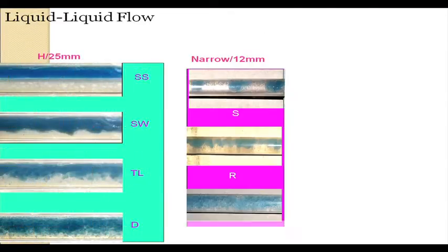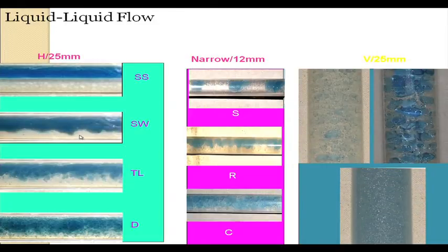Now, in this particular case, we find that due to the higher surface tension of the liquid, it cannot assume the shape of the elongated plugs as we observe in gas liquid cases. On the contrary, when the waviness is very much, then it shears the interface, and therefore, there is a large amount of droplets of both the phases entrained at the interface between a continuous kerosene phase and a continuous water phase. This did not happen for horizontal air water flows, but in this case it happens because the liquids tend to remain spherical and they are not stable at an elongated shape. So, therefore, after stratified smooth, stratified wavy, instead of slug flow, we get a 3-layer flow pattern, and as we increase the velocity, we find that one phase gets dispersed into the other.